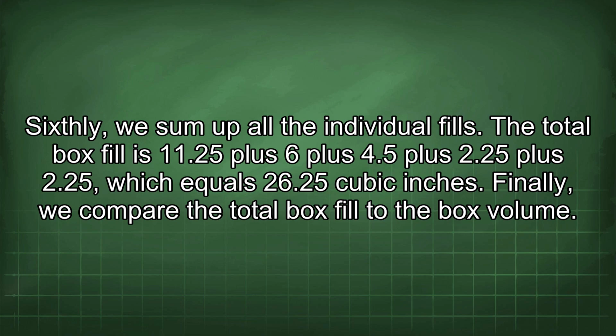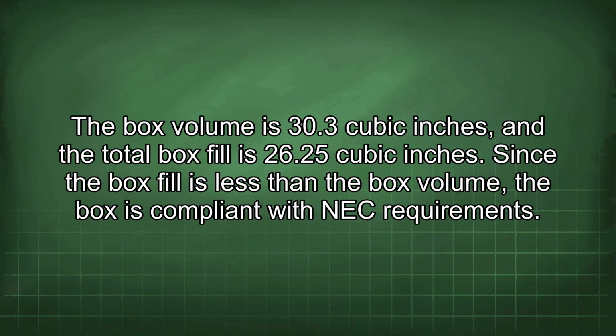The total box fill is 11.25 plus 6 plus 4.5 plus 2.25 plus 2.25, which equals 26.25 cubic inches. Finally, we compare the total box fill to the box volume. The box volume is 30.3 cubic inches, and the total box fill is 26.25 cubic inches. Since the box fill is less than the box volume, the box is compliant with NEC requirements.